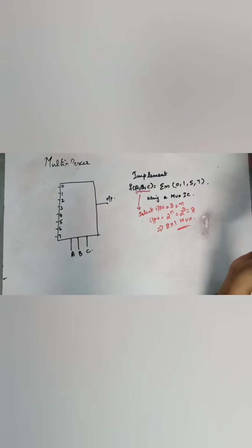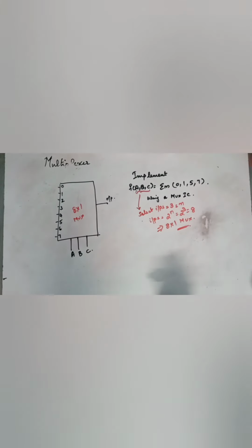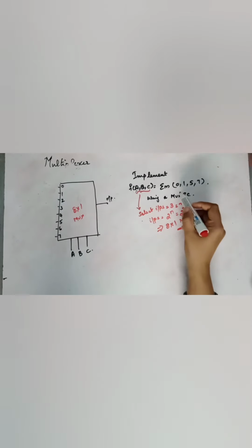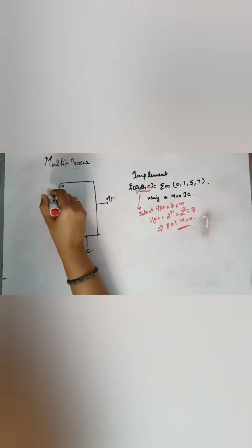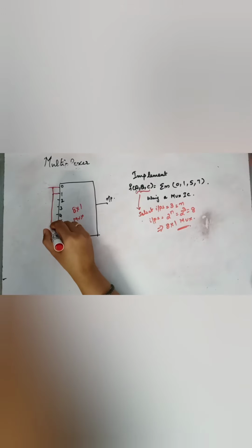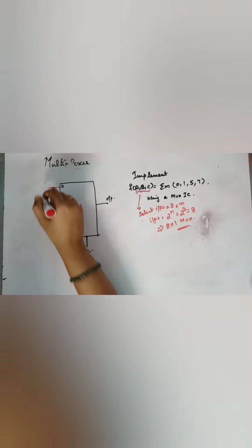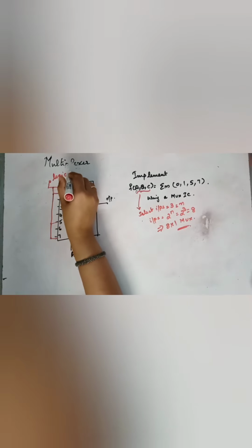Then to implement this using the 8 by 1 mux, I have to connect the input lines 0, 1, 5 and 7 to logic 1.